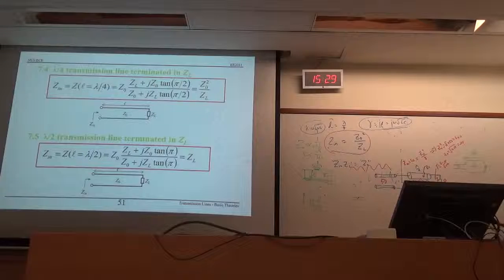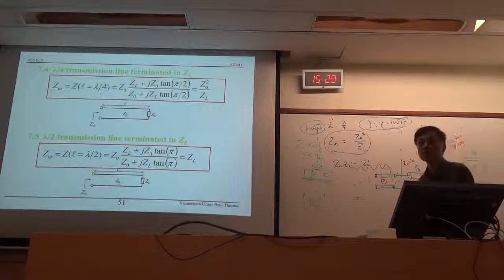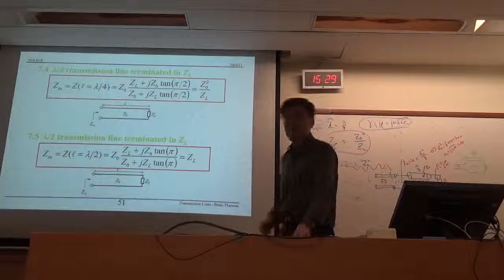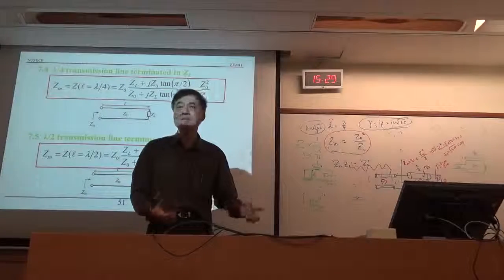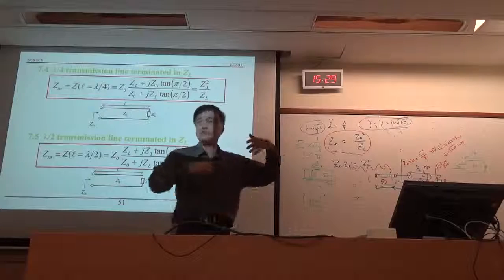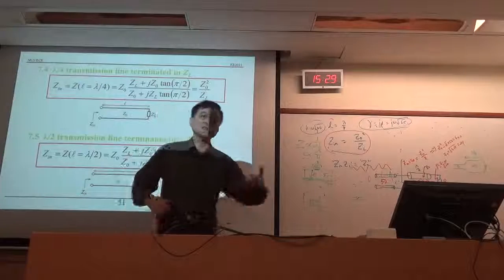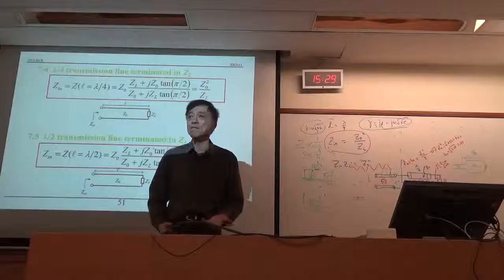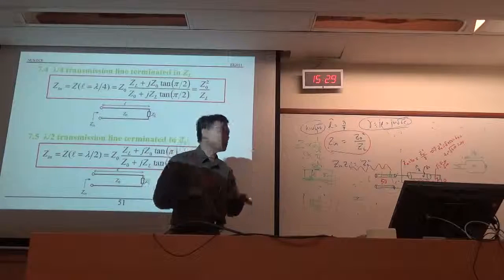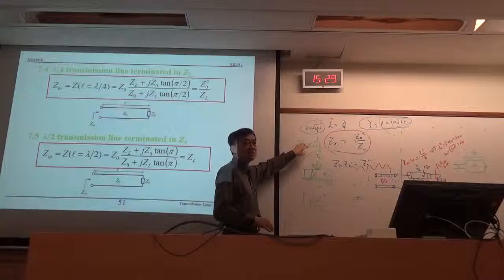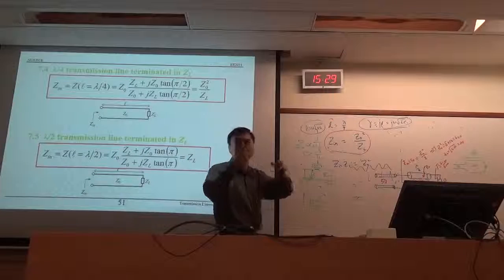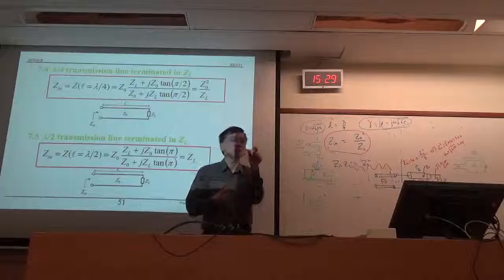So that is one way to do matching. Of course, if you use a physical line, you can't always do it, because sometimes the Z0 that you require comes out to be a very fancy number, like 26.5 ohm. How do you do that? But 26.5 ohm is no issue when you use a strip line, because you can design it by controlling the width of the strip line.